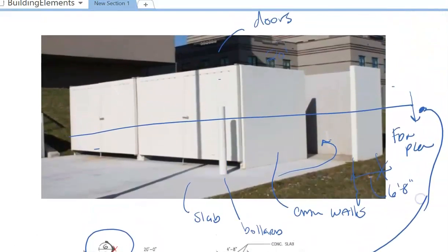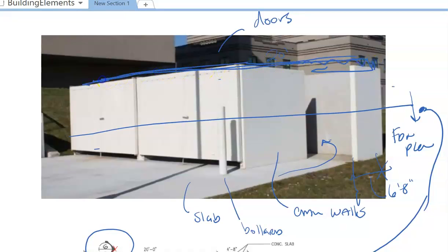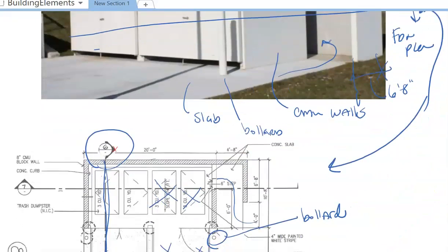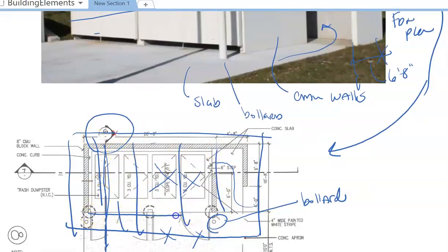And in our assignment, we also decided that we wanted to put a roof on this, right? So the rain and things like that wouldn't get in. And so when we make that roof plan, we're going to make the cut up here, and we're going to show it in a separate plan, because if we showed it all on the same plan, for example, if I started drawing the roof in here, and I started drawing the purlins, and I started drawing the beams, it's going to be difficult to read because there's going to be too much information.